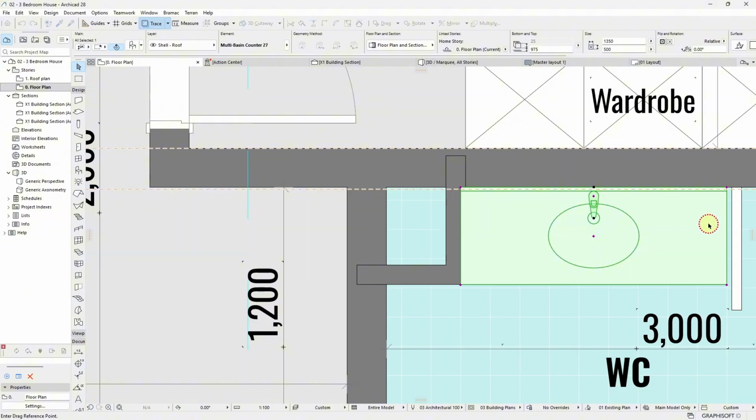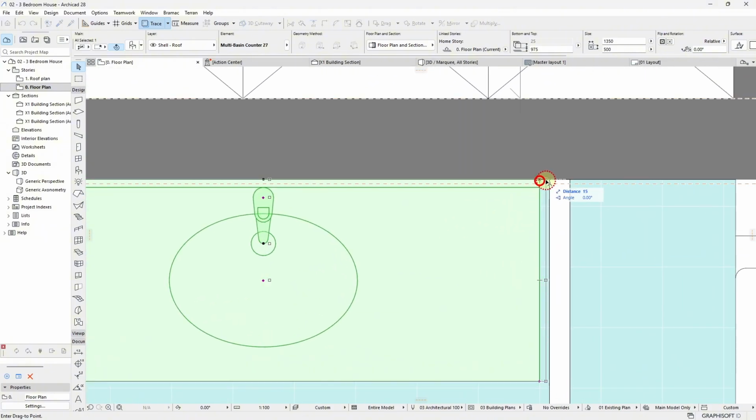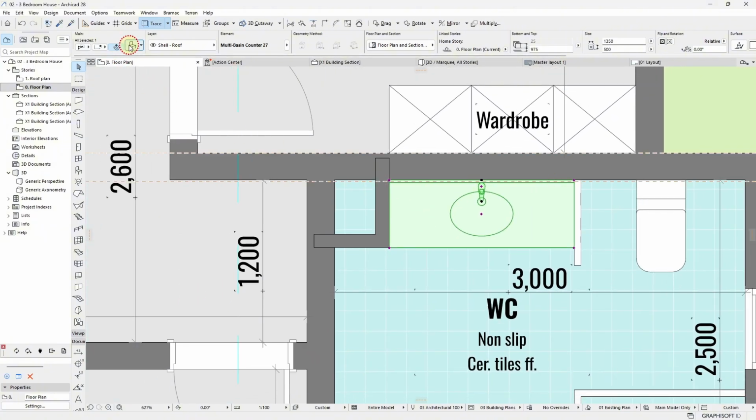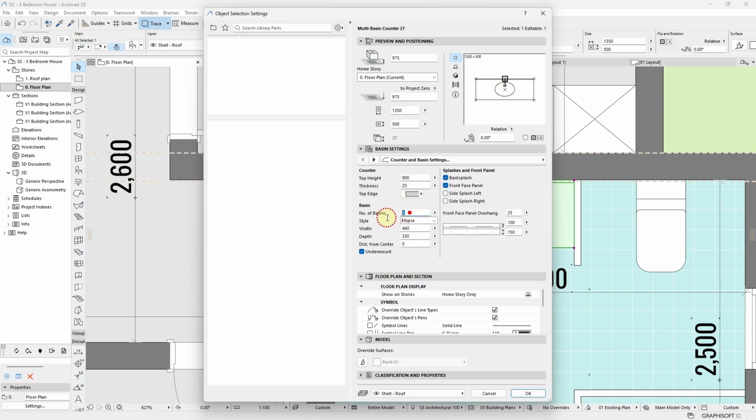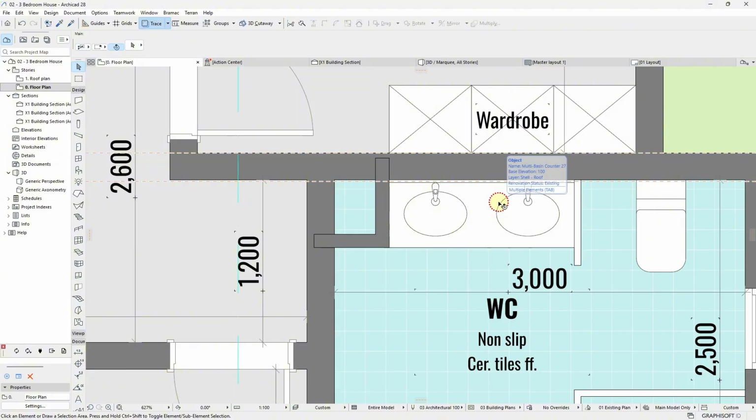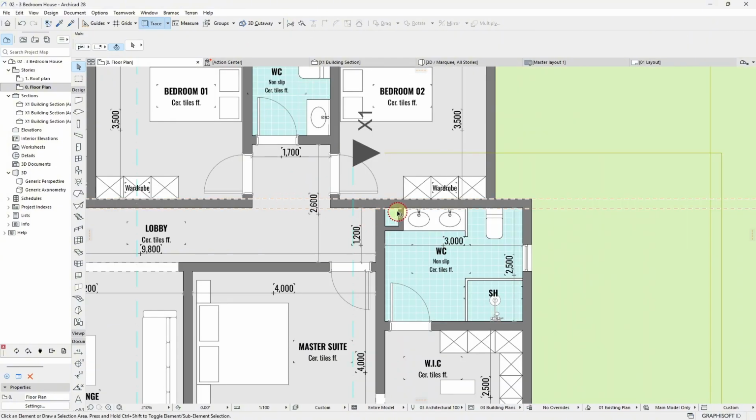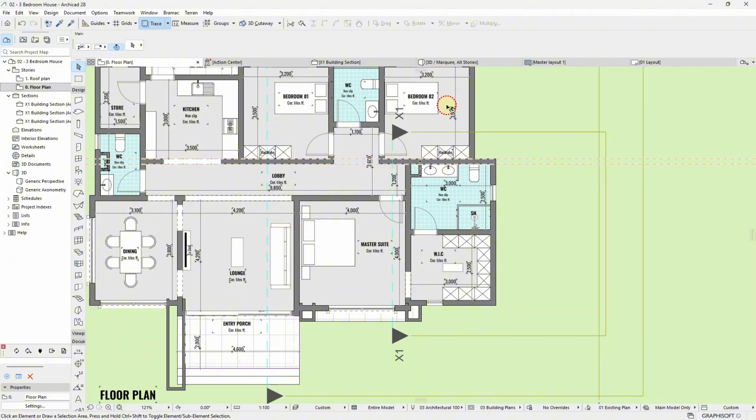And then I want it to have 2 basins still. I'm going to give it 2 basins. Part of this roof can be drained into this gutter, and then it is passed through the floor slab to go out directly. So at least we have 2 sides of drainage, so that when it rains heavily, at least we have enough outlet for the water.